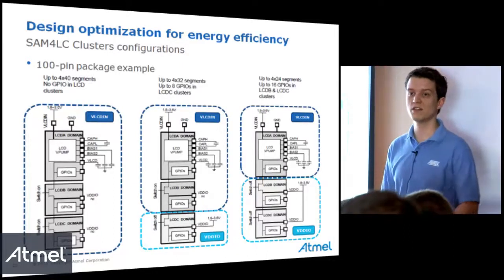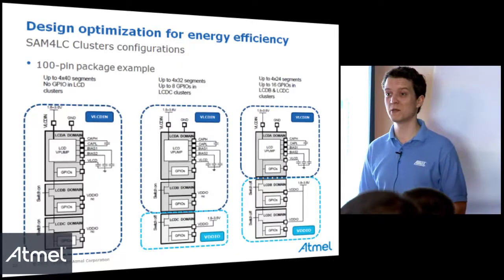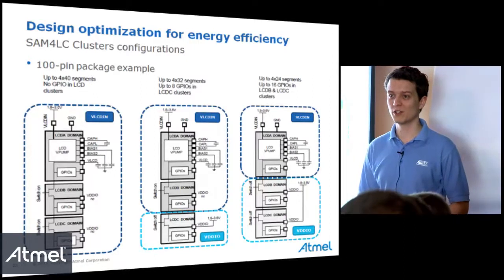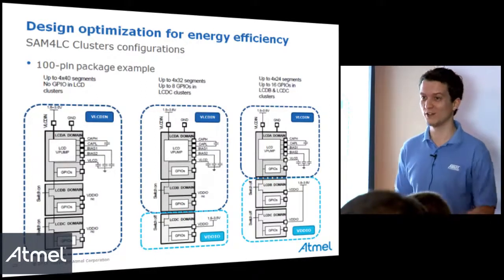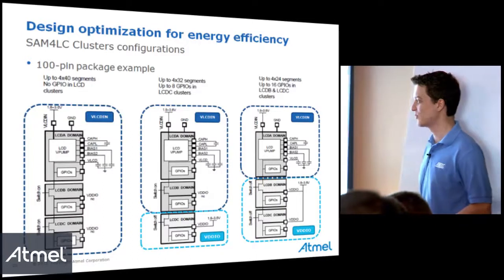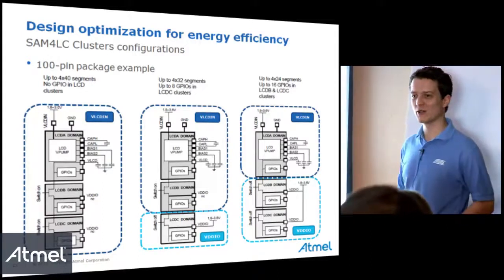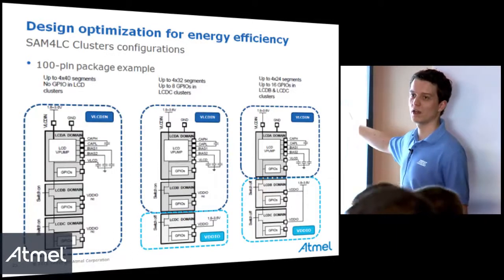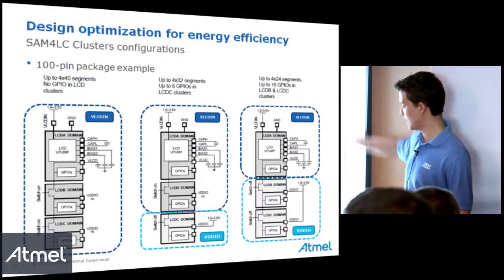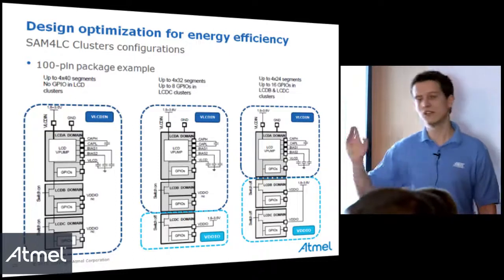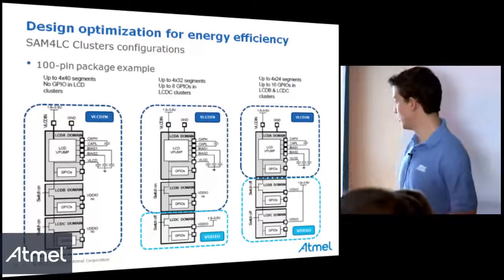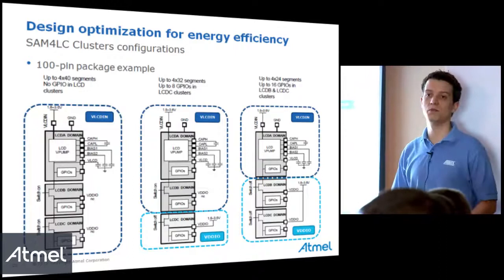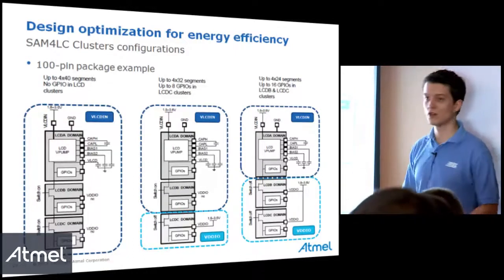First, it means that you've made a mistake when you selected your product, because we have a product that does not embed the LCD controller. But if by the way you want to use this, you can just put VLCD in at the same level as VDD IO, and then you will be able to use all the pins as standard GPIO. Any question on this subject?